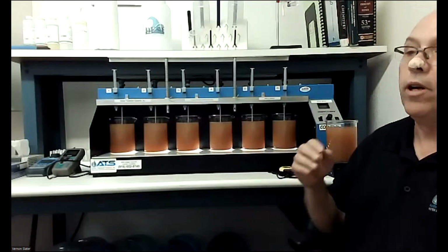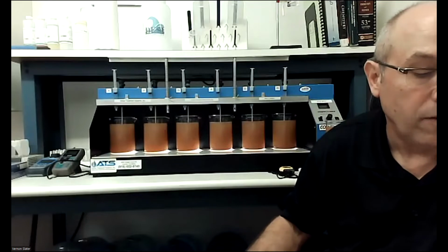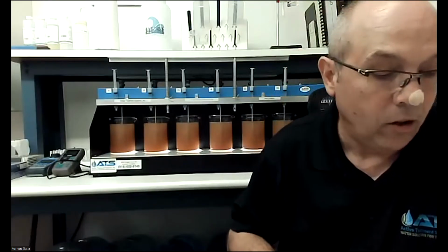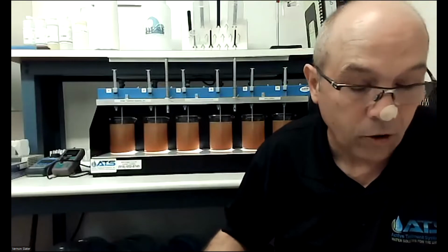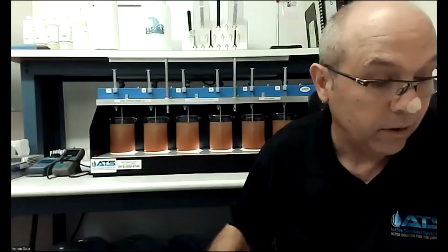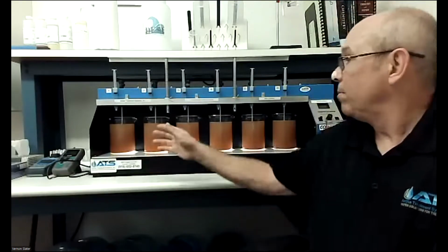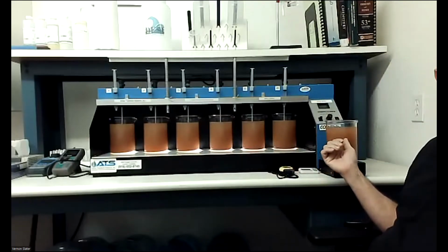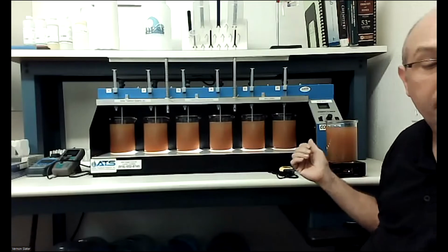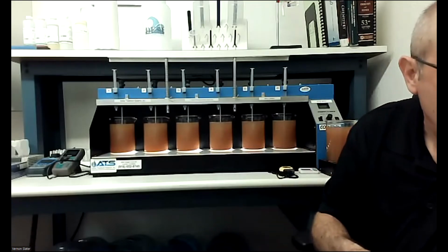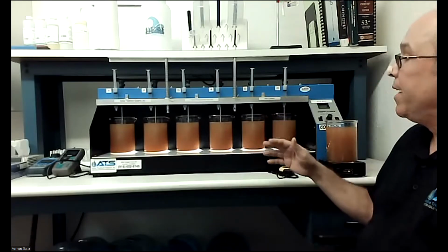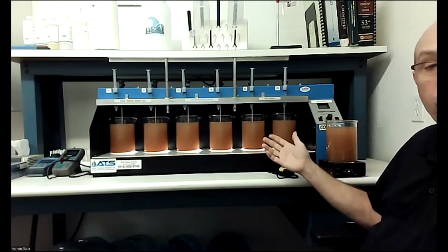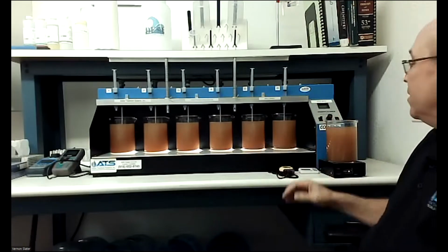In the laboratory, we grab 5 to 10 gallons of actual site water sample, or we produce simulated stormwater using distilled water and actual site soil samples. We set 6 jars up like these are set up, with one to represent a control sample that does not get any coagulant added. And then we flash mix, and we settle, and we see what the reactions are after 5 minutes.